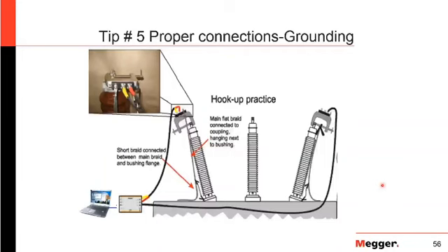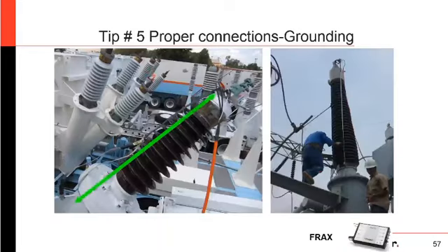So looking here, preferred grounding practice: shortest braided ground. Poor grounding is when you just have ground floating around, and this could be curled up or this could be laid out flat. And because the inductance of those loops change or the impedances change, it'll vary the results in that high range frequency. So by doing the shortest braided ground and having solid connections, you're going to have repeatable results there.